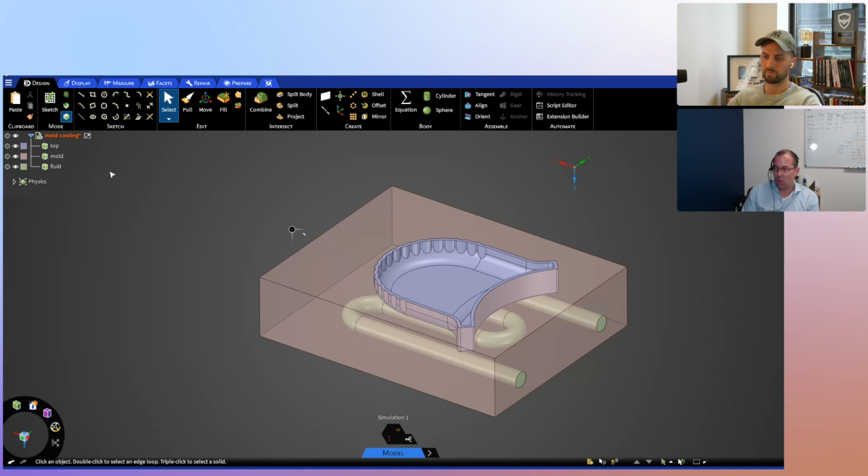And sometimes if you're doing a lot of top-down design, what I mean by that is in mold design and in plastic design, a lot of times we're doing surfaces and curves, and we're driving our solid geometry from other geometries, right? So think about a large team of people. One person's going to own the industrial design, that's the surfacing, and then other people, the engineers, let's say, are more concerned with the physical stuff. So you've got this CAD file that's crazy. It's got edges, surfaces, solids, and a lot of times that's not a nice geometry to bring into a STEP file or IGES file and then try to bring into another CAD.